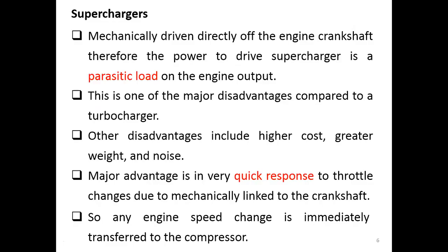Okay, let's first talk about superchargers. As we already know, it is mechanically driven directly off the engine crankshaft, right? So the power to drive the supercharger is considered to be a parasitic load on the engine output, because some of the engine output, instead of being delivered for us to use, has to be given to the supercharger in order to run it.